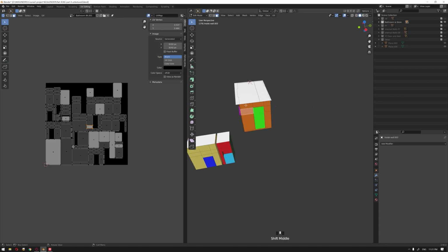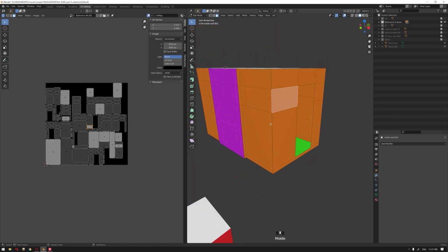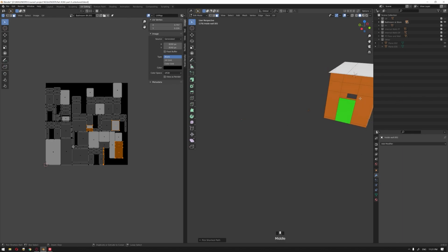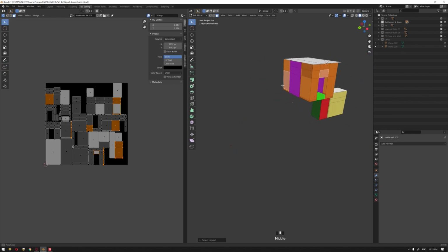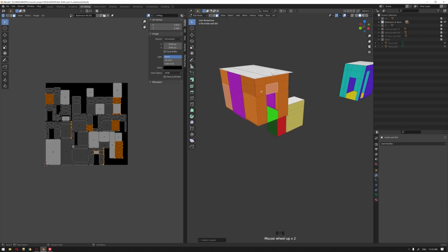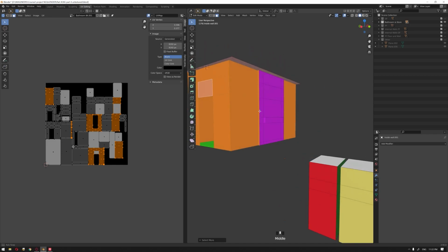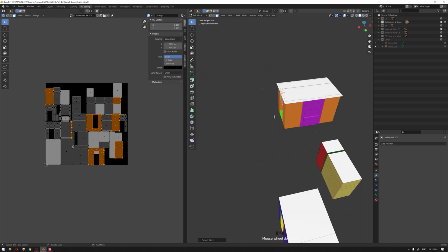So before we start, what we want to do actually is that if we choose for example all of these walls that have the same material, by either pressing on L it will select all the faces, so I can choose all these walls together like that, and pressing L it will select all the materials. If it didn't select them all, you can hit Control, and by the plus sign it will increase the selection up to the last face that have the same material. So all our faces is now selected.